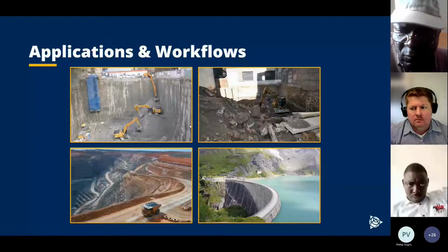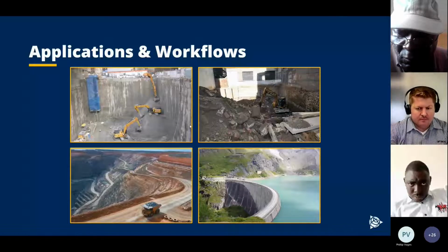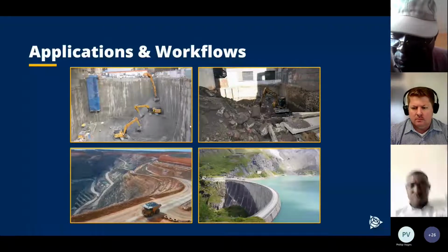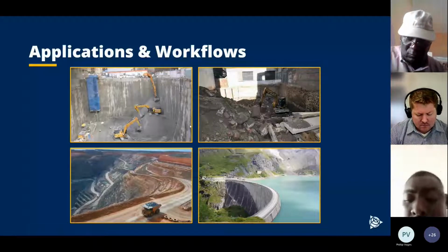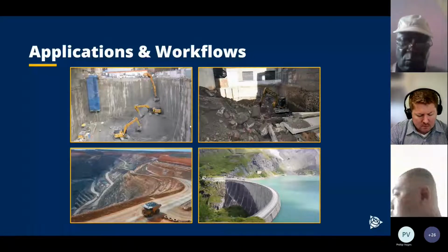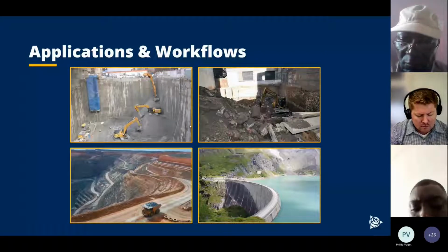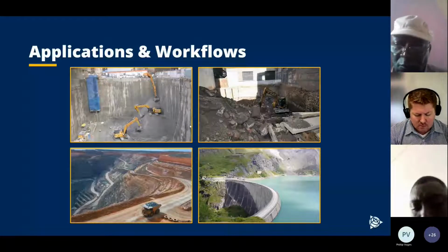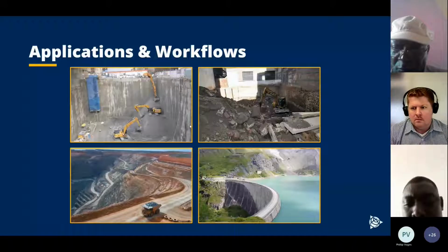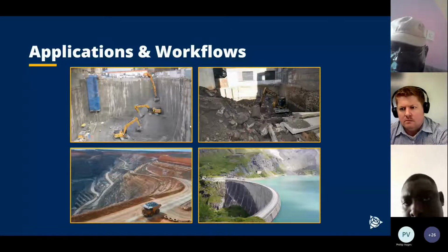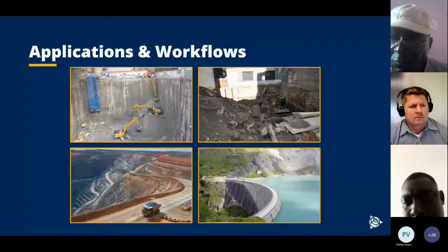And another one on the bottom right side is, of course, hydro dams. Hydro dams need to be monitored. Monitored in real time with geodetic instruments? Not necessarily, but at least you will go there, for example, at least twice a year, when the water level is high and when the water level is low, or maybe after heavy rain, or whenever there was a very quick rise in the water level. So these are typical applications where you can take your total station and do some measurements on these objects.